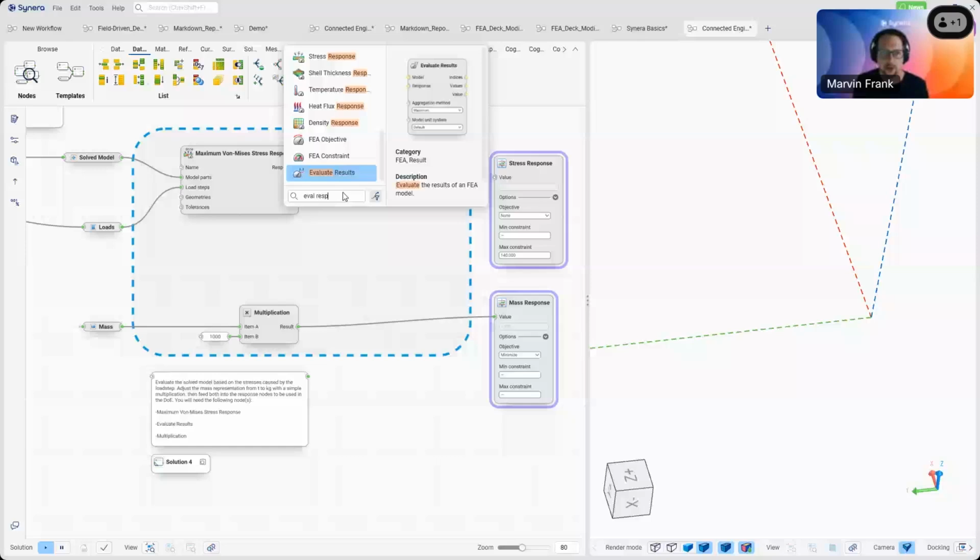So the second node after the parameter setup is the design exploration. And here now it's easy because I've already set this up. So I've just added designs here. You can do that with the plus buttons. And then per default is 100, but you can also use like 10. I just added 3 because the topology optimization is running. So I won't do that now because it takes some time. Even though it's simple and just I think 8 minutes or 15 or something, but we don't have that time now to wait for 15 minutes 3 times. So I already set this up here and let that run before.